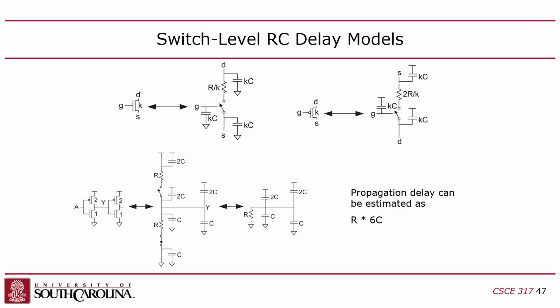Okay, but then also, that's just the driving side. Then the receiving side is this guy is going to drive two gates, right? There's the pull down gate and the pull up gate of the second pair of transistors. And so this is the gate capacitance. So I've got another 2C capacitance on his pull up and C on his pull down.